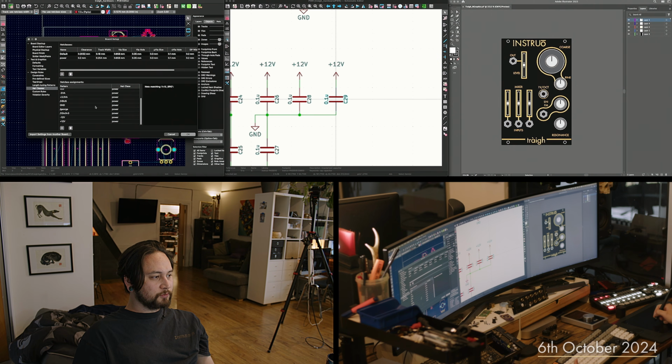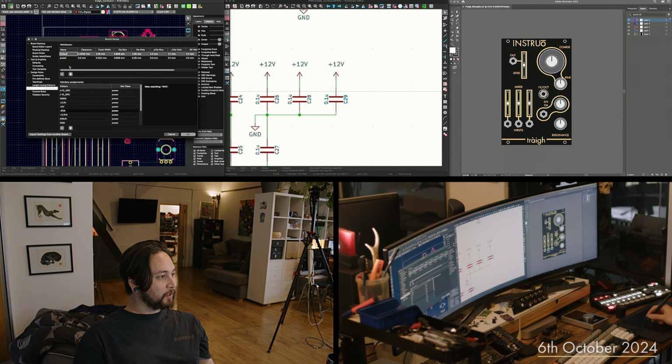These were imported from, I think it was the dial project files. I imported that when I was in the schematic side of things. So I just pulled in a bunch of the net classes for power, which cover all the main bits that I use. Plus 5 volts, plus 12, minus 12, ground. There's a bunch of other ones as well, whatever power line George was in that previous board file.